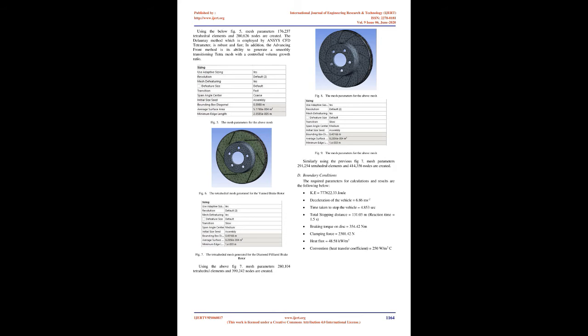A solid brake rotor. The cross-drilled holes help in moving the air from the brake surface, thus reducing the surface temperature. They also eliminate hot spots and warping of the rotor. Chamfering the holes and the various edges reduces the possibility of stress cracks. The optimum number of holes are drilled to provide the right compromise between the structural integrity and cooling.